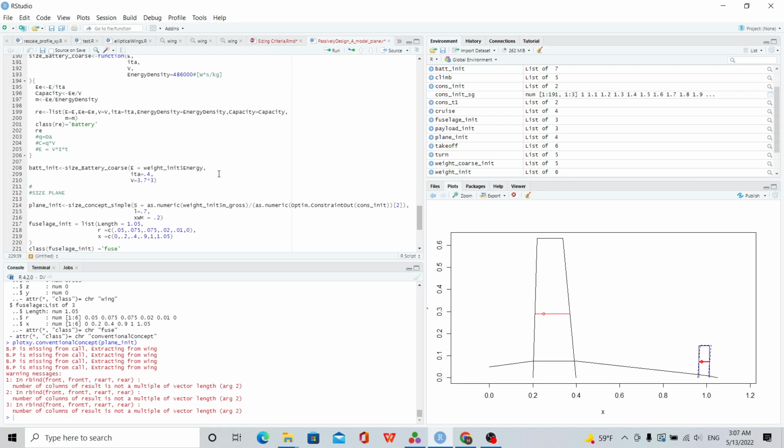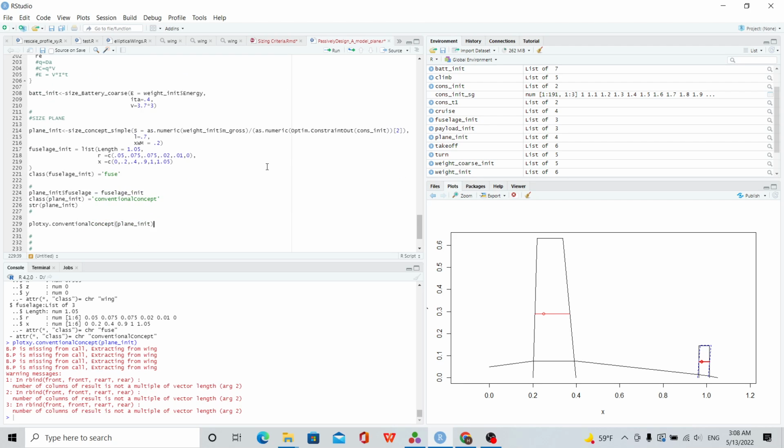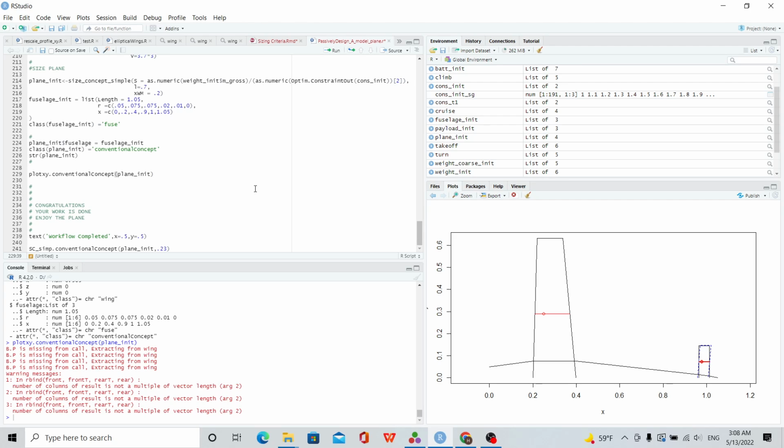Because if the payload, the weight, the thrust weight ratio, and the wing loading are determined, then the rest of the part is just aerodynamic calculation and how you want the plane to handle.